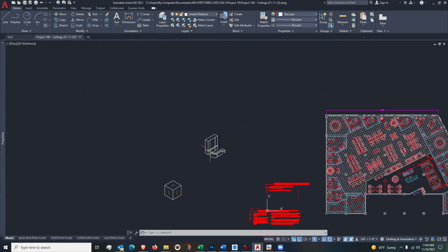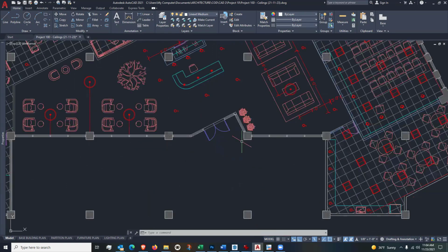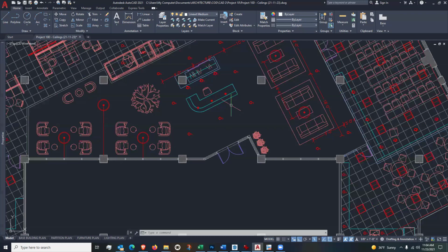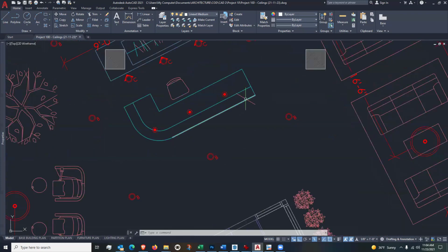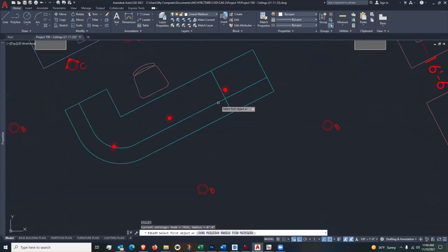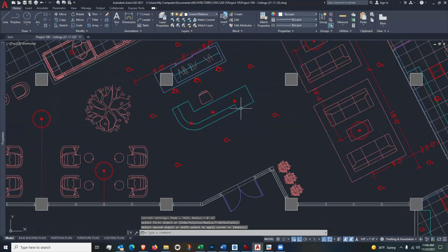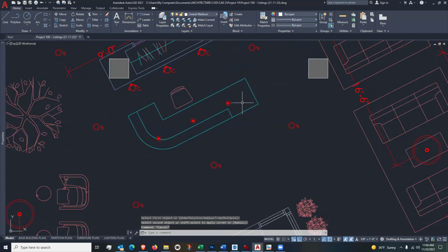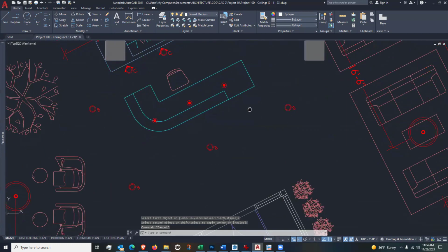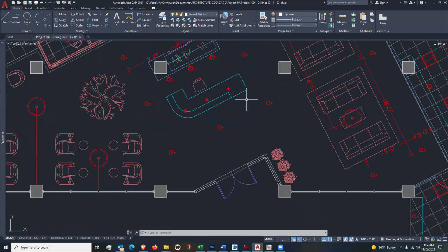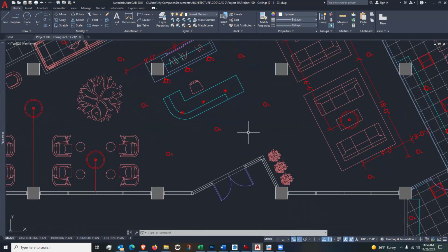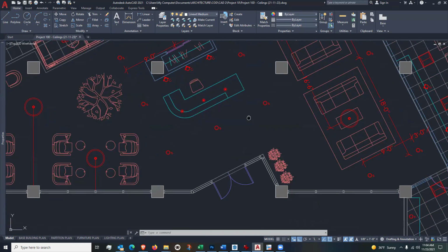Now, if it were me, let me go back to the floor plan here. So, this isn't showing this right, is it? If I were actually showing this right, this should be 36 inches, and it should be like that, right? So this is the low portion where a handicapped person can come up and do some transaction, whatever they need to do.